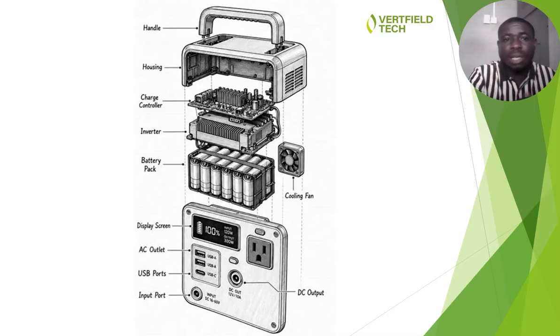In this picture, you can see the housing, the box that contains your various solar components. You also have the electronic charge controller there, which you can use to charge the batteries from your solar panels. You have the inverter system there, which helps you convert the DC energy from your panel or from your battery system to an AC output supply source. You also have the battery pack there, which is the storage facility, or we call it the energy storage facility.